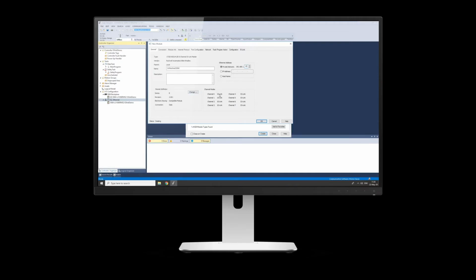In here you'll see it says channel 0 IO-Link, channel 1 IO-Link, channel 2 IO-Link, and so forth. So this module can actually have 8 IO-Link channels. I know at the moment I'm only going to use one of them as IO-Link, so what I can do is disable the rest of them. But what you could also do is use them as normal I/O. So you could have a digital output on the second channel of port 1.